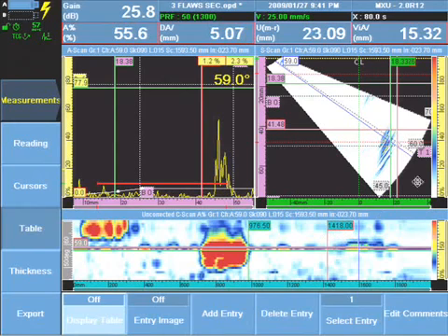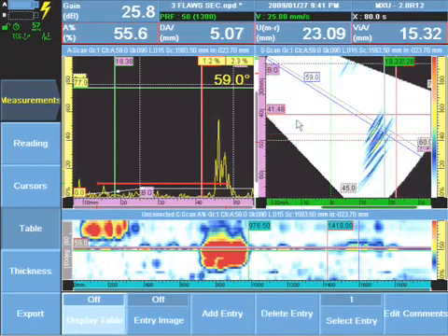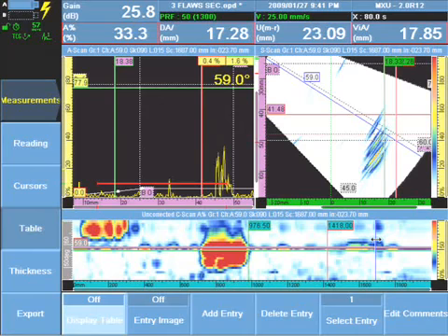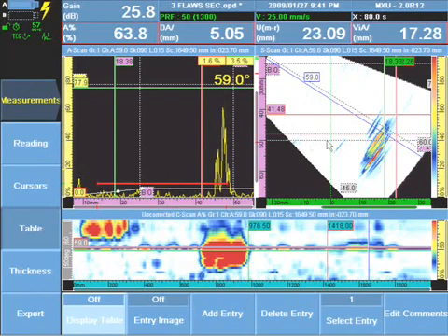and as I move into the next flaw, we see a different type of indication in the S scan and in the A scan. Notice the multiple jagged peaks and edges, long rise and fall time, multiple tip diffracted signals. We know this is connected to the surface because it plots right at T1. We have a very clear, sharp, multiple peaks indicative of an outside diameter crack or toe crack.